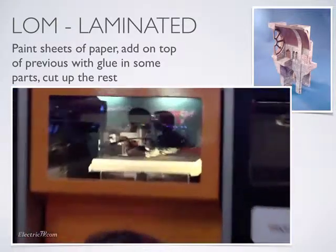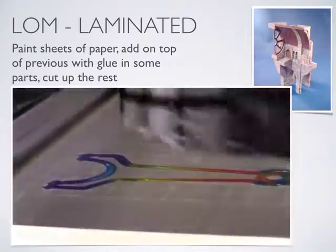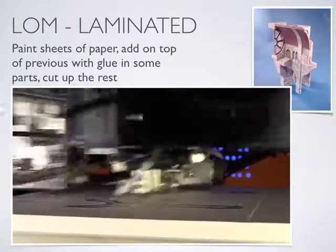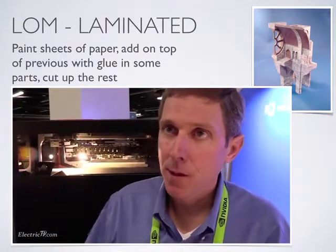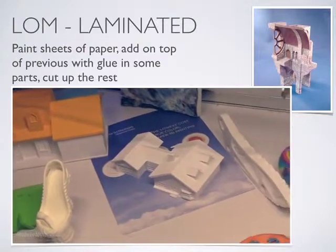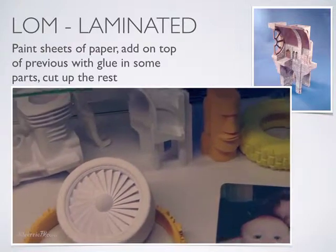Once we color our paper, we feed it through our system here. It feeds in one sheet at a time. So we take a sheet of paper, we cut the cross section for that particular layer using a tungsten carbide tip. Then we apply adhesive to that layer. And then we add the next sheet of paper, and we just repeat the process over and over again until you get a stack of sheets of paper. And we pull that out, and then you remove the excess material, and you have your part or parts inside.